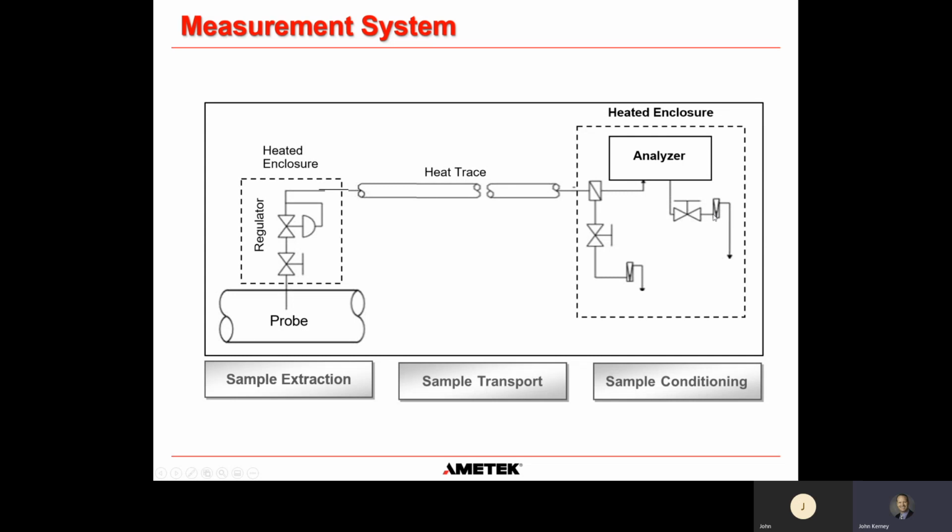I guess a related question to that is, does the rotometer cause any back pressure on the analyzer, which is really an excellent question. There's a couple of different ways you can operate an analyzer. If I was designing just, say, a very basic sample system for compressed air measurements, I might have an inlet valve and a filter.